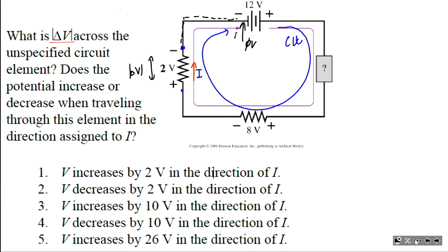We say the voltage across this resistor is equal to 2 volts. But from point 1 to point 2, potential rises. So we say there is potential rise from 1 to 2. However, from point 2 to point 1, potential decreases. So we say potential drops. This is just slang electricians use, but sometimes it's also used in a textbook or in a problem. This is just a voltage with the indication of direction of basically electric current.